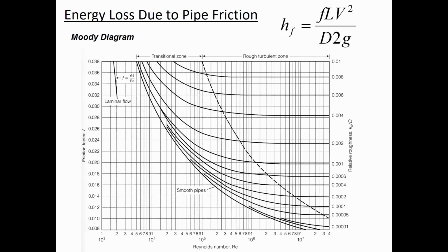So the power of this Darcy-Weisbach equation is in part related to the fact that the Reynolds number you're calculating is very specific to the actual flow conditions that are in that pipe. So you'd have to find your Reynolds number based on what is the fluid, what's the diameter of the pipe, and what's the velocity that water is going through the pipe. And so we're in between these two lines, and you'd go up until you intersected with whatever your viscosity is.